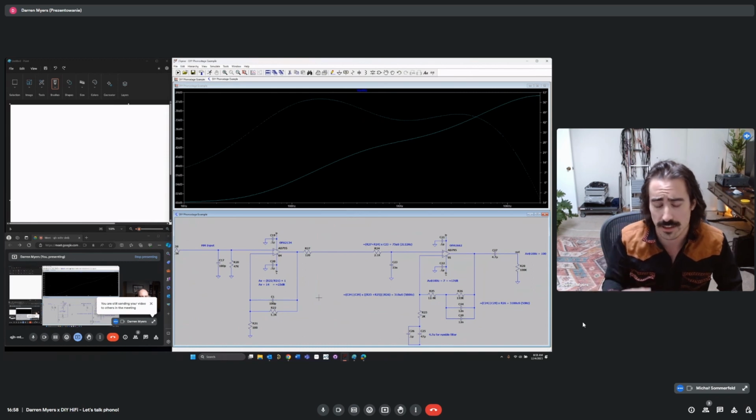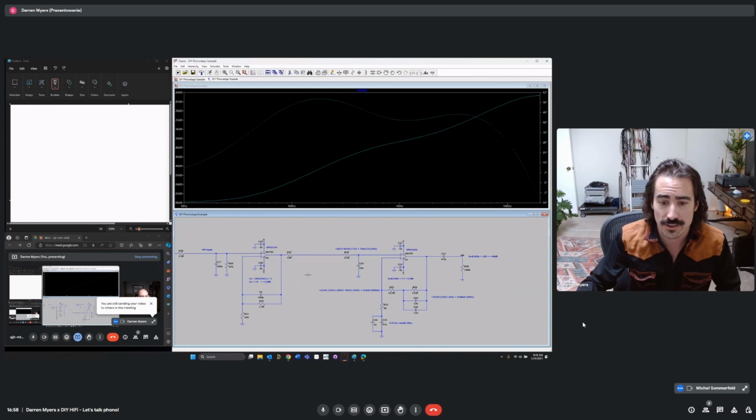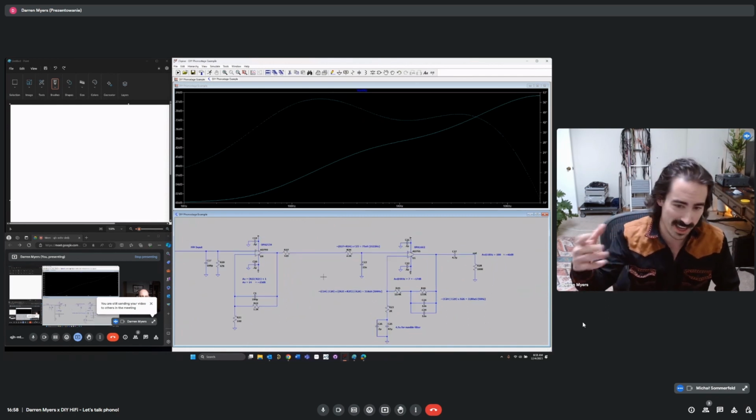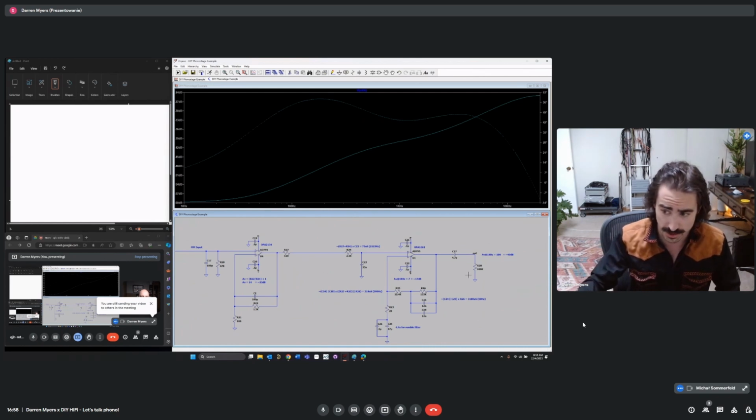And that's something when we're looking for op-amps for phono stages, op-amps that have a very low input offset spec, generally that's a very good start because we have so much gain, and the gain is going to multiply that input offset and put it right on the output here. When you think about it really quickly, you're like, well, it's just so small, but it adds up so quickly. So at low frequency, we do not have 40 dB of gain.